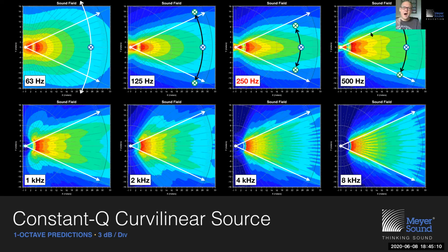But then as you go up in frequency once more, at 500 Hertz, abandoning the regime where line length and shape are the driving force, the loudspeakers are omnidirectional, starting to progress into that part of the spectrum where the loudspeakers become highly directional, become point and shoot, then you see that the beam opens up again because we're sending the sound where we want it to go. And at 1 kilohertz, you also see that the beam width starts to conform with that slice of pizza. And from 2 kilohertz, 4 kilohertz, 8 kilohertz and up, it's essentially that slice of pizza which was already predicted in 1940.